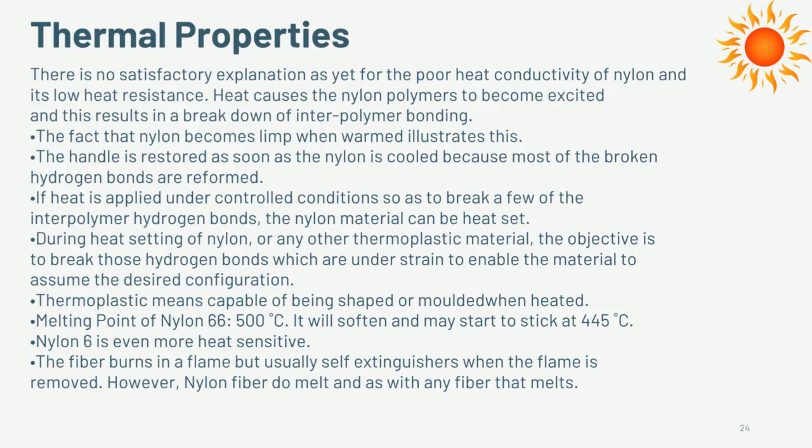Thermal properties: there is no satisfactory explanation as yet for the poor heat conductivity of nylon and its low heat resistance. Heat causes the nylon polymers to become excited, and this results in a breakdown of interpolymer bonding. The fact that nylon becomes limp when warmed illustrates this. The fiber burns in a flame but usually self-extinguishes when the flame is removed. However, nylon fibers do melt, as with any fiber that melts.